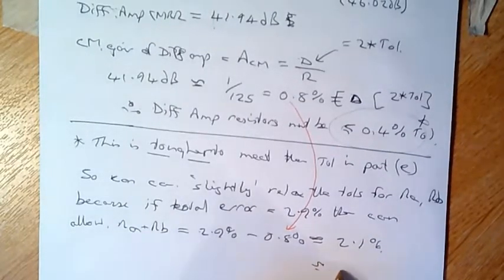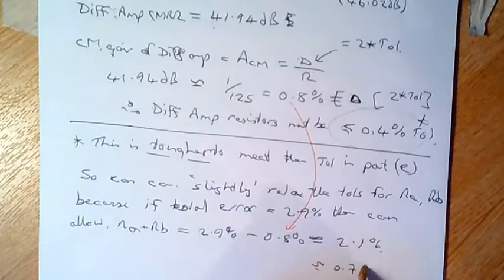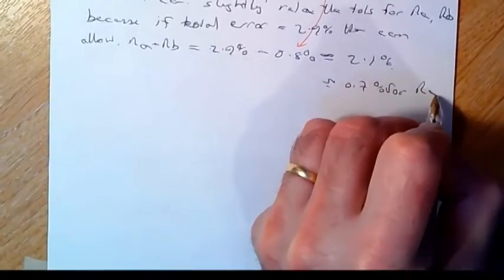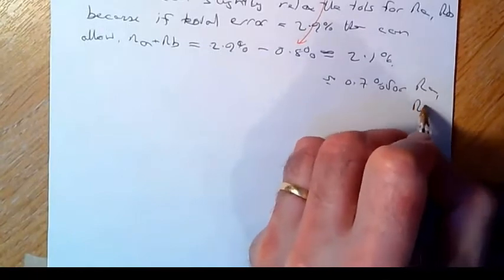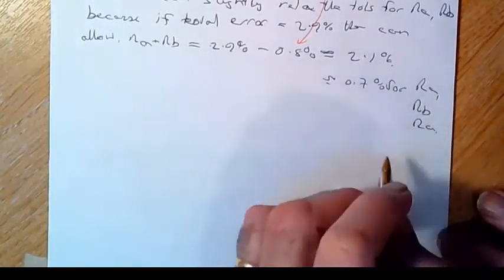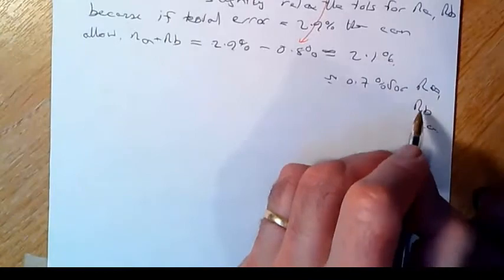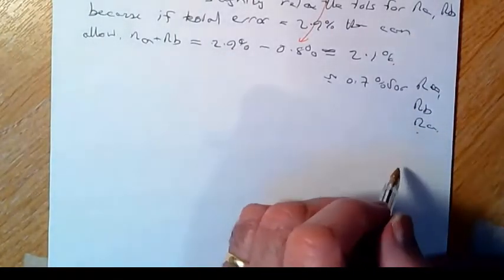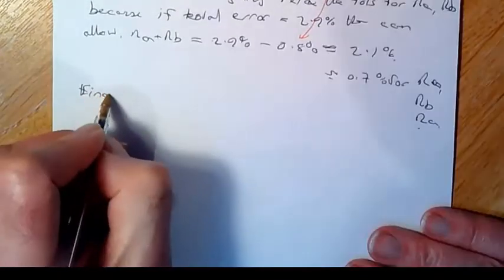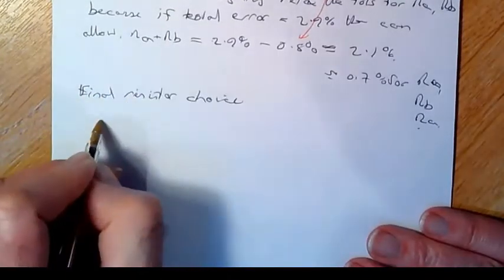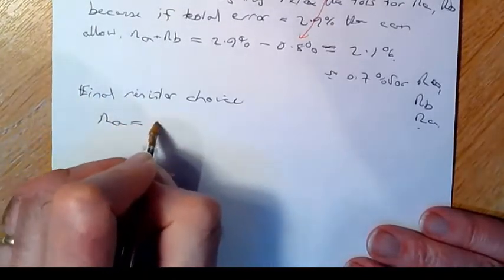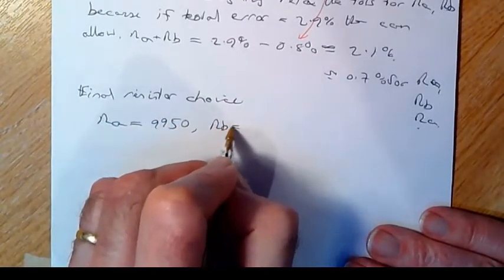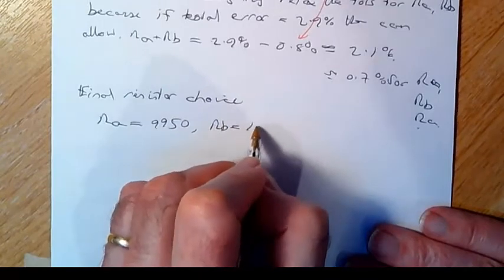Which is approximately 0.7% for RA, RB, and RE. Remember, you've got two RAs here, and they're separate resistors, so you still have the combination of both. Final resistor choice, RA equals 9950, RB equals, what was it, 100 ohms,